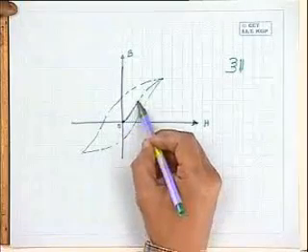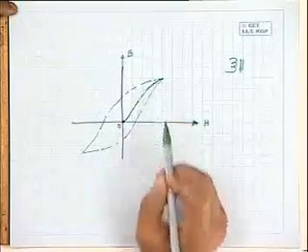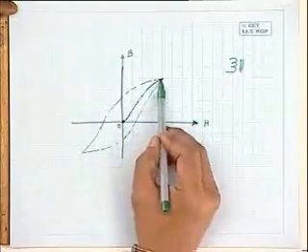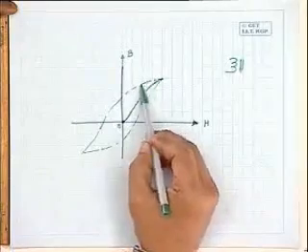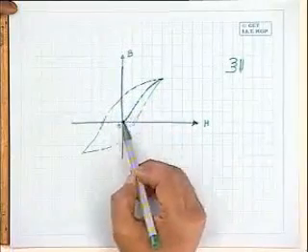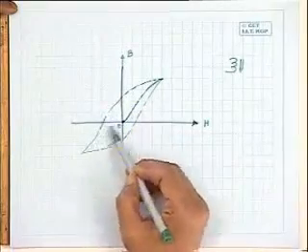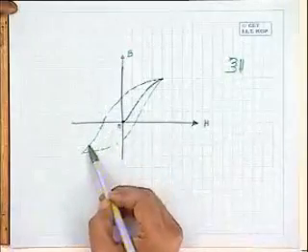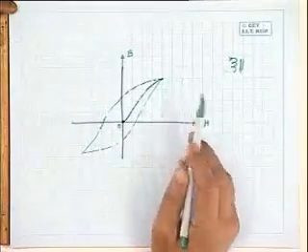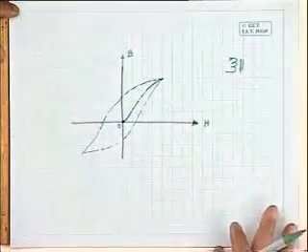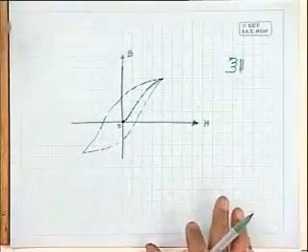Now, when there is no residual magnetism, H will increase and B will increase like this. It will start from this point. Now, if you decrease current, because of retentivity, the path traversed will be like this. And if you now give negative current, that is, initially current was flowing like this, now flows like this, then it will go this way. This loop is obtained in a BH material.